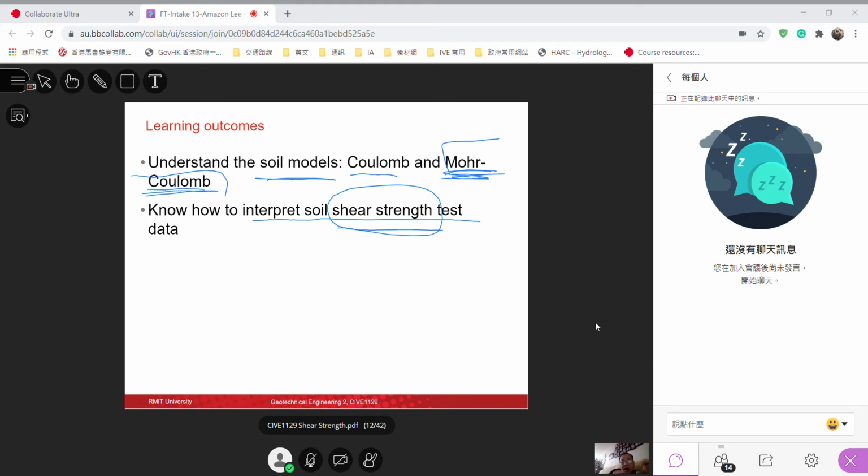So the common types of civil engineering construction material, whether it's concrete, structural steel, or aluminum, get most of their strength from the bond strength. The particles are bound together either through physical nature or through chemical nature. But soil is not; it's a non-bonded material.